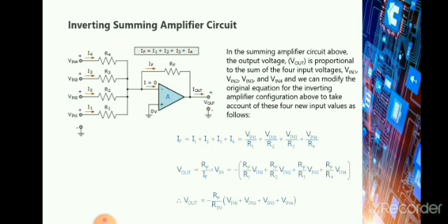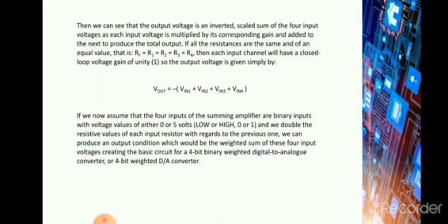So since we are using an op-amp as an adder circuit in our DAC, which is an application. So this is how an op-amp generally works. These are the normal general equations for finding V out and IF of the op-amp alone. So this op-amp is basically used as an application. We have DAC, that is digital to analog converters. Also in analog to digital converters we can use op-amps.